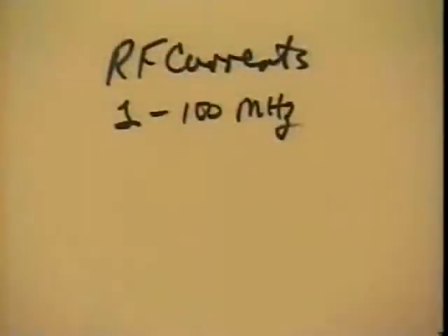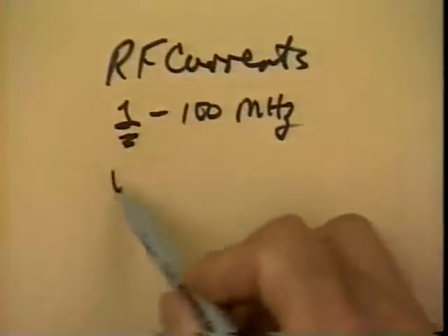Everything below 1 megahertz we don't care about. So we can put a little series capacitor in our signal line, block out all that 60 hertz and 540 hertz and 180 hertz and 2 kilohertz frequencies and not have a problem. We're not interested in what's going on at low frequency as far as our signal is concerned. So because the low frequency end is not that low, we're in good shape. RF currents, like they're typically run on multiply grounded coaxial cables, that's not a problem. But supposing we have a video signal.